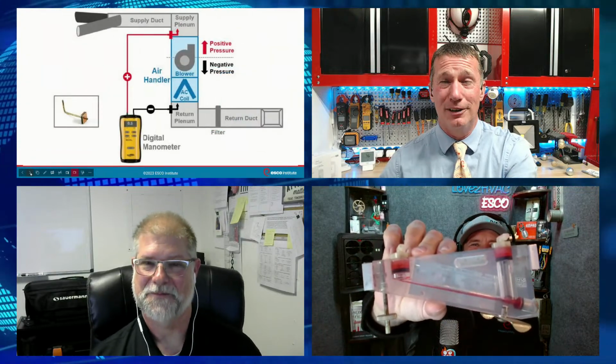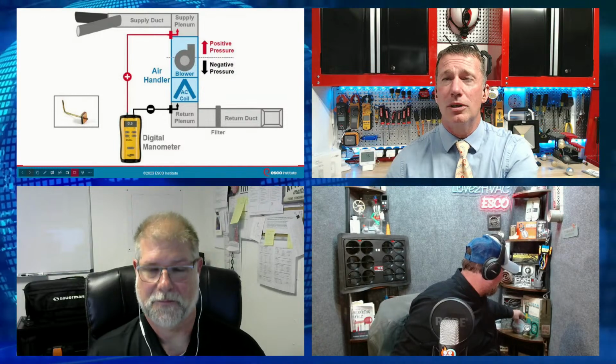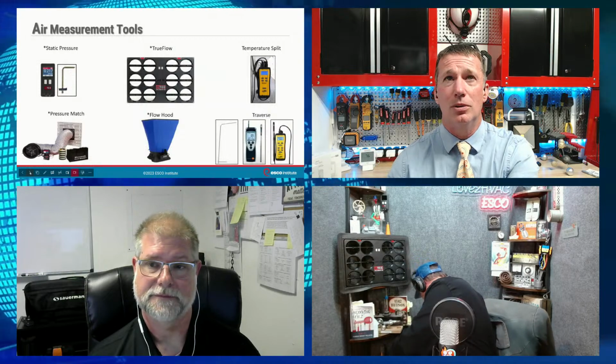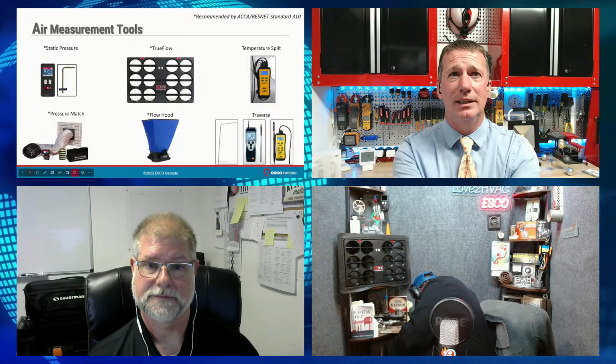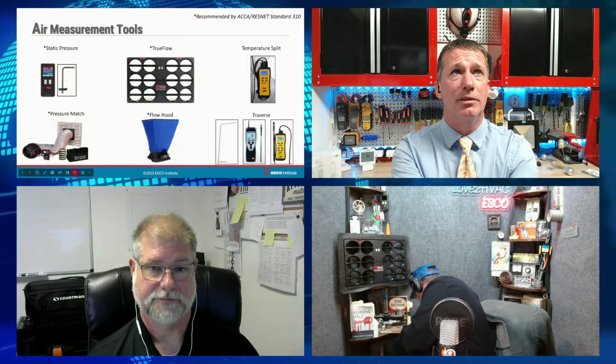So basic fundamentals, when we start talking about measuring static pressures, we've been measuring static pressures for almost 100 years in water column forms, right? We've used the Magnehelic. Ty's got one right there. That was the practice that we used. I've even seen some of those original ducted systems that had Magnehelics installed in the ductwork, especially on zone systems. And so when we start talking about professional measurements, of course, we've seen digital technology, like using digital manometers. But let's go a little further and talk to people about ways that we can get even better, more accurate measurements of our airflows.